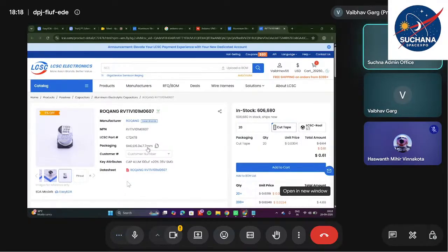So these are two different ways to place a component in EasyEDA from the LCSC library. Basically, LCSC and EasyEDA have collaborated with each other. You can place components from the LCSC library inside EasyEDA. I will tell you how to do that. Go back to the schematics page.